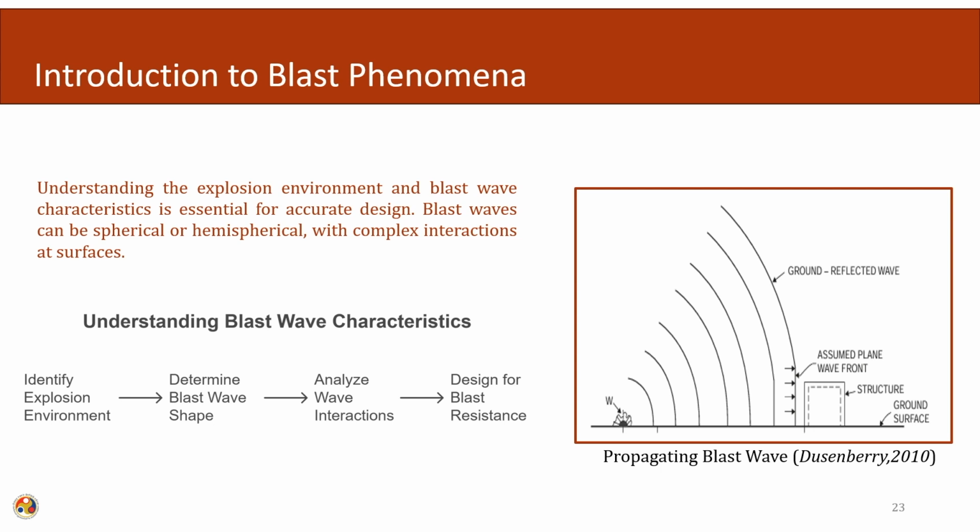In the figure we can see the explosive is kept on the ground, so it becomes a case of a surface burst. The waves are travelling outwards, and once they hit the structure, the reflection occurs, and then we categorize this as the reflective wave or the reflective pressure.